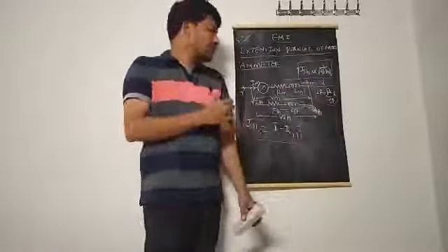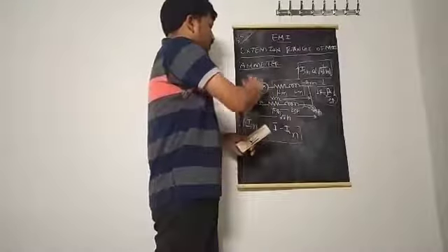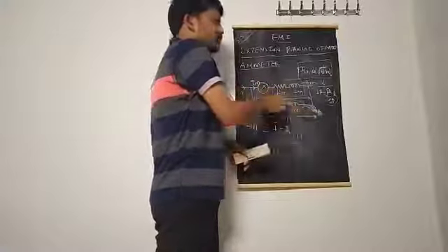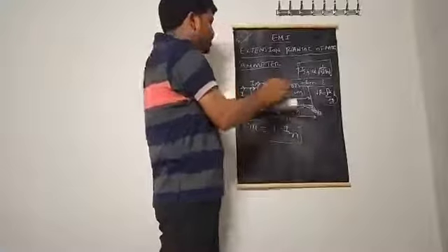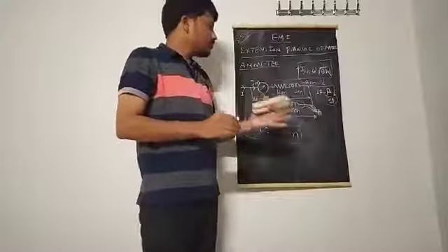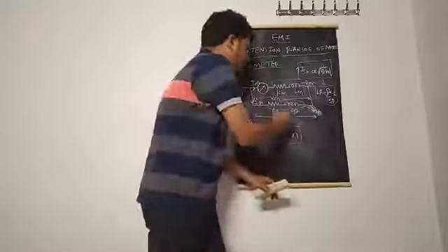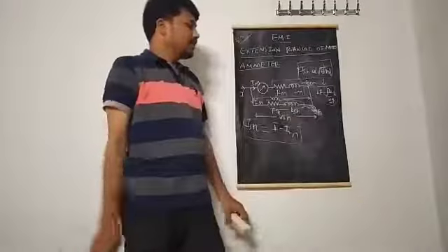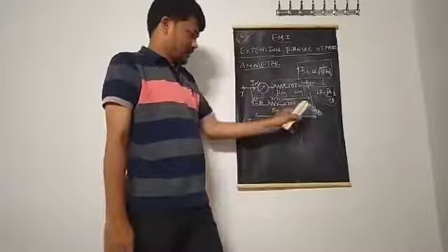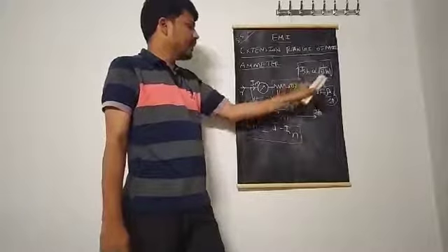So coming to the derivation, I think all of you are clear on this topic now. This is the complete equivalent circuit of the extension of range of a moving iron meter as an ammeter. Without the ammeter, the equivalent circuit of only the moving iron meter is just the upper part. To solve this problem, RM and LM is nothing but impedance, which I take as ZM, the impedance of the meter. RSH and LSH is the shunt impedance, which I represent as ZSH.